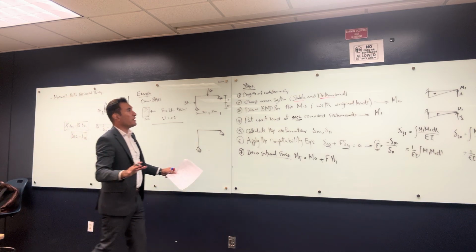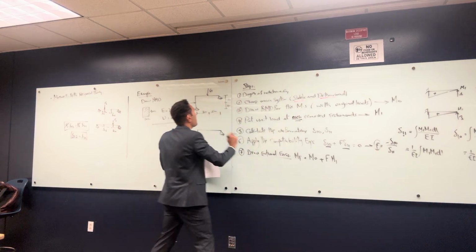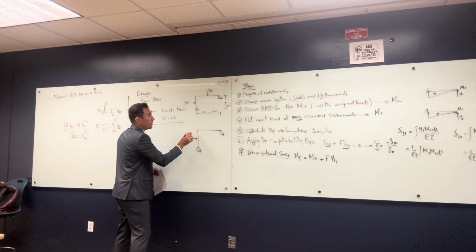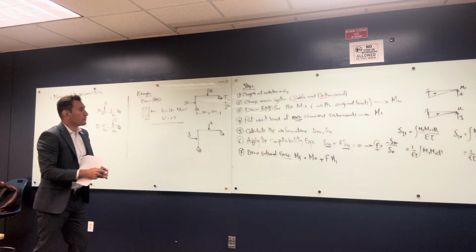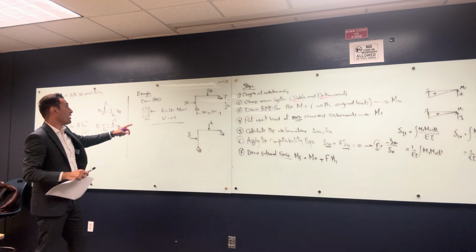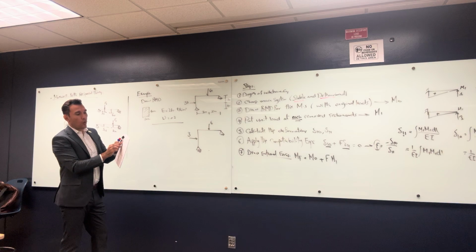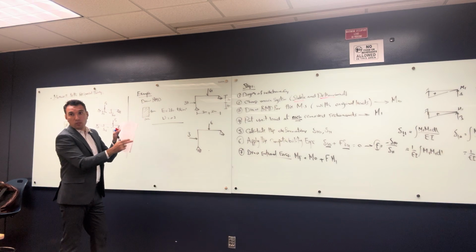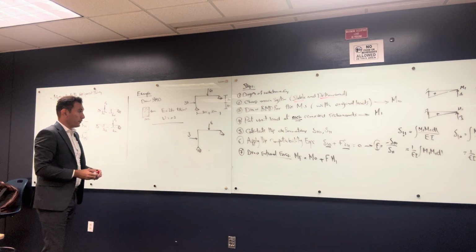All right, that's the main system. The main system needs to be stable and determinate. I'm gonna put the original loads on the main system, the 3 and the 6. What I'm gonna do is this, you are gonna get the reaction and draw the bending moment, shear, and normal. But right now, I only asked for the bending moment diagram. Here, I said draw all the internal forces diagram, so you have to draw normal, shear, and moment. But I'm gonna deal, for the sake of time, with only the bending moments.